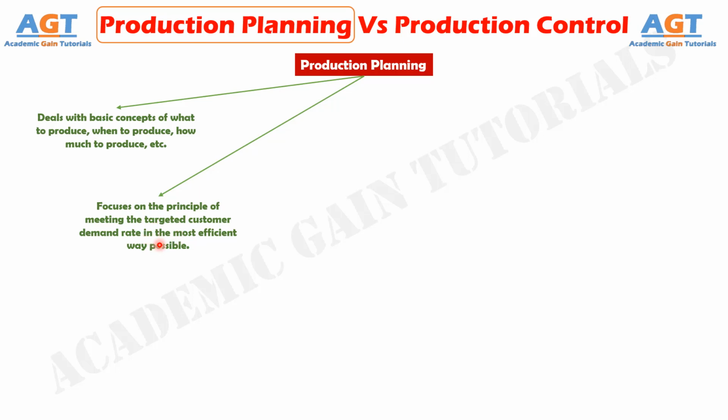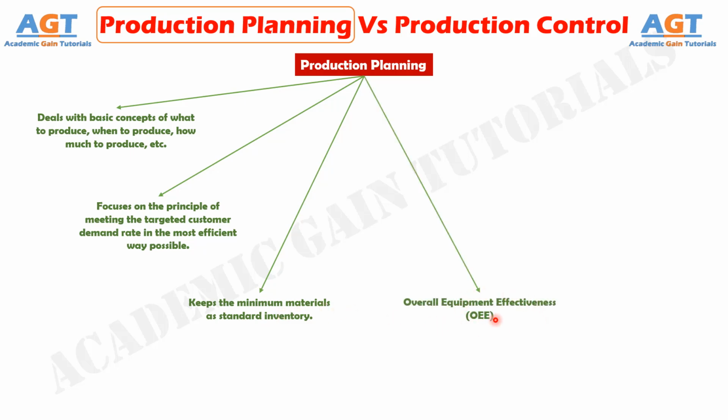This assesses the requirement of different materials to fulfill your production target and their availability. Inefficient production planning keeps the minimum materials as standard inventory. Planners must evaluate how much material the company needs, the lead times for orders, the delivery times for suppliers, and the reliability of the suppliers or vendors. Production planners take into account the capabilities of the machines or equipments used to produce the output. Basic stability of an equipment is ascertained on the basis of three parameters, namely, its availability, its performance, and its quality. This is done by overall equipment effectiveness.